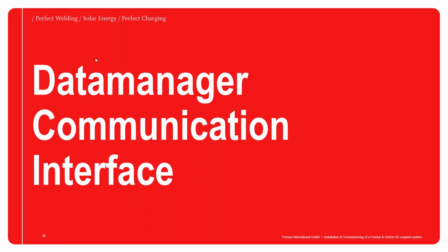Okay, we will now move on to the next part of the Fronius presentation, where we will be looking at your data manager communication interface. As my colleague Cyprian did mention, it is compulsory to have at least one Fronius inverter with an integrated data manager. Please do note, for any Fronius inverters that are bigger than 8.2 kilowatts, the data manager will come as an additional optional extra. Any inverter smaller than 8.2 kilowatts does come with an integrated data manager. So please do take note of that, and please be aware when you are ordering your inverters from your distributor.